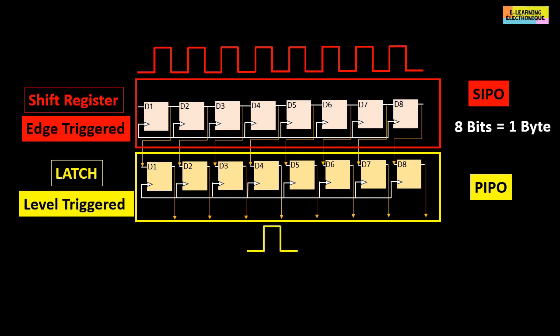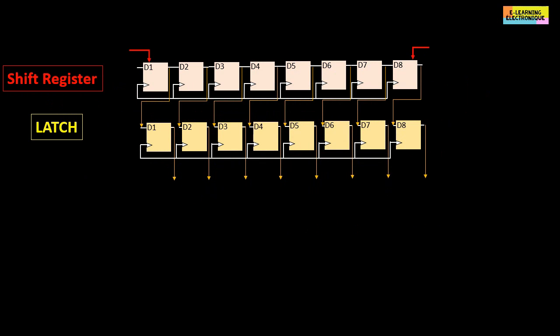At the shift register we find the STH signal, which is an abbreviation of horizontal start. It is the signal of the beginning of horizontal scanning. The shift register is often of bidirectional type. This allows the data to be read in both directions. To specify the direction of the data reading, the letter R of the word right, or L of left is added to STH, which gives STHR, for a reading of the data from the right to the left, and STHL, in the opposite direction.